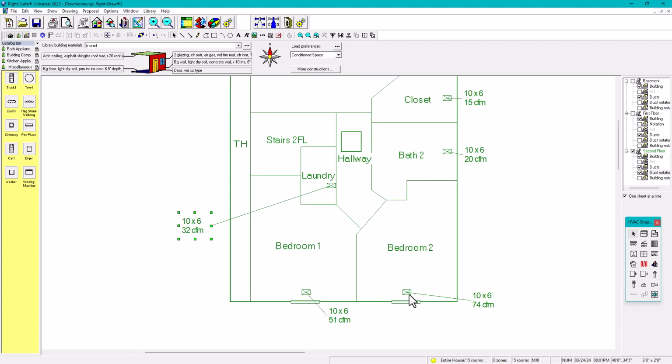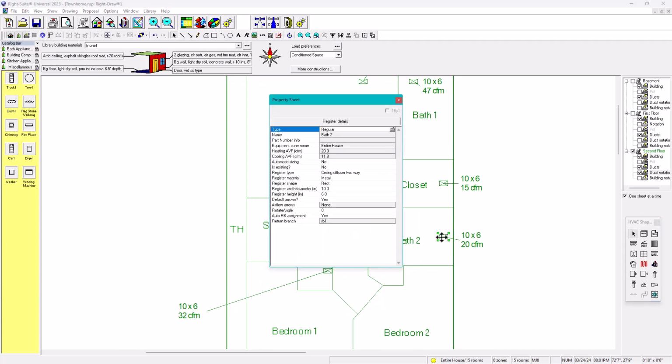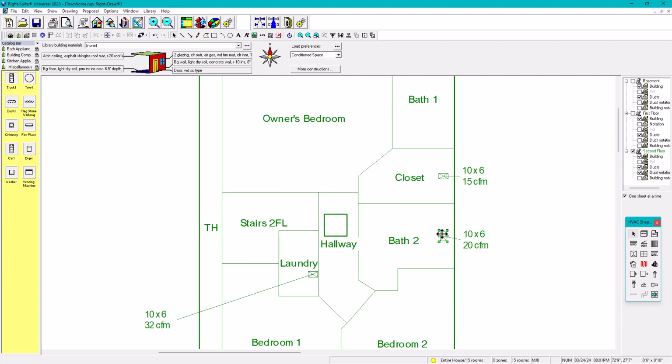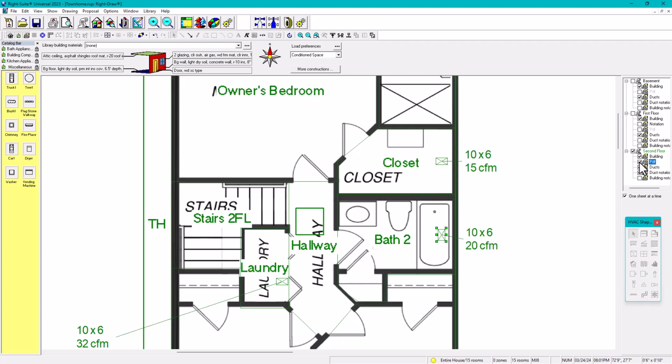However, in here we're doing perimeter, right? So everything is in the perimeter for now, right? Here. And we can change this to 90 degrees. Okay, rotate angle, 90 degrees. There we go, right? And then, so how is this oriented? It's better to see, that's why I have my PDF. Let's check the PDF, go to the tree, check PDF, see, are we gonna have my register above the bathtub where the shower is? I don't think so, right? So in other words, we're not gonna do that. We're gonna move it to the side, possibly here, right?